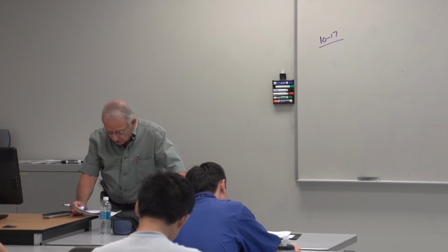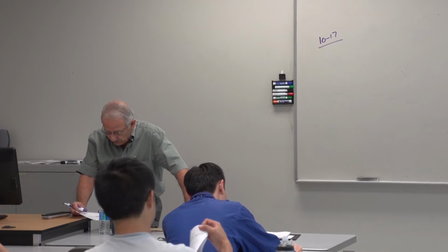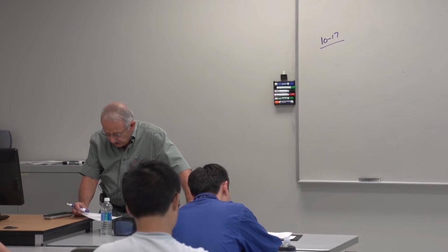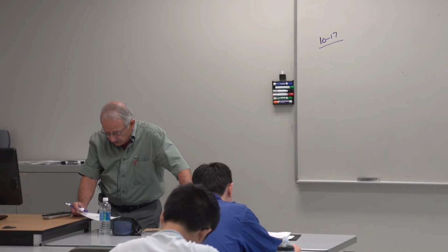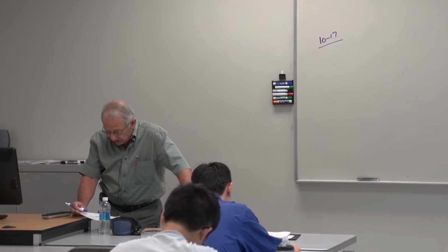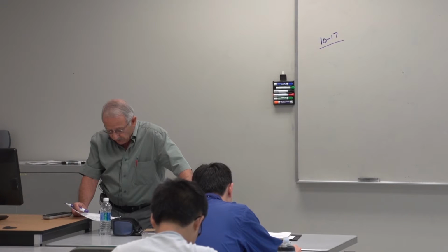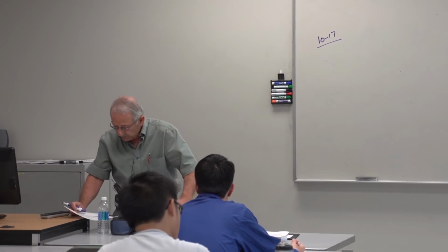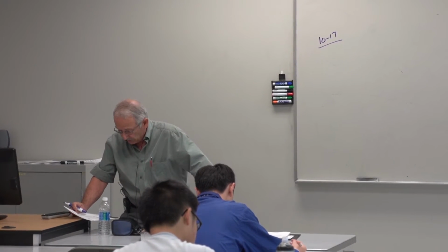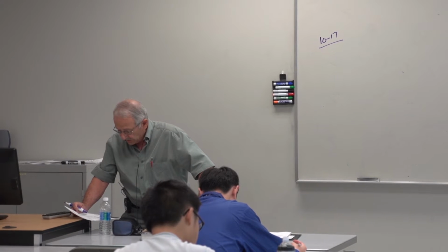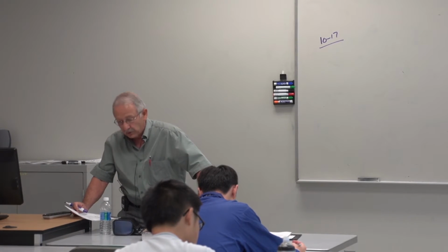So in this problem it says a uniform 3/8 of an inch diameter rod AB of length 9 feet is made of a high strength stainless steel for which sigma y equals 125 ksi and E equals 28 times 10 to the 6 psi. Knowing that a strain energy of 50 foot-pounds must be acquired by the rod as the axial load P is applied, determine the factor of safety for the rod with respect to permanent deformation.